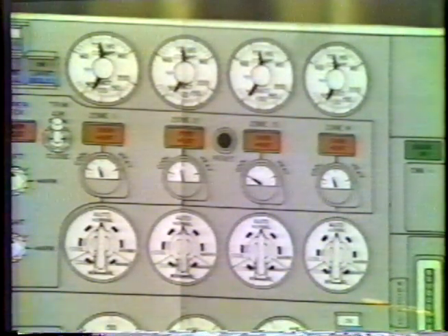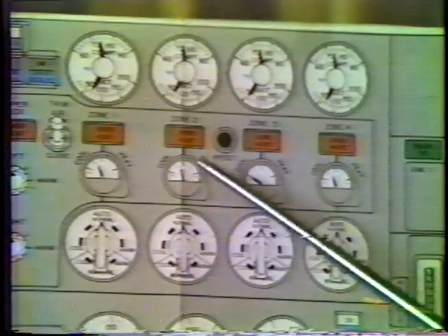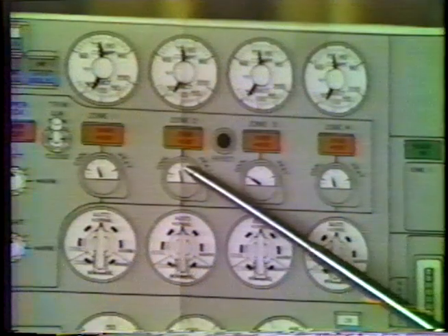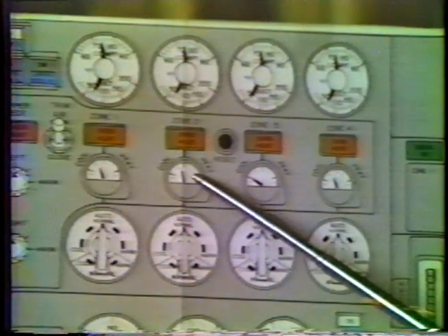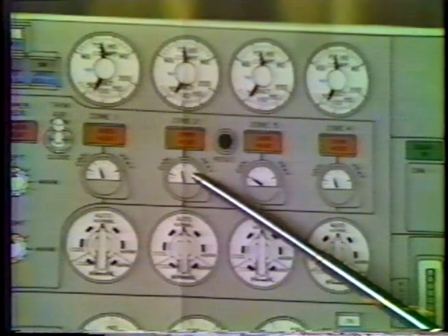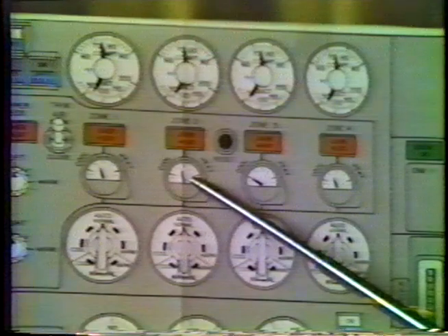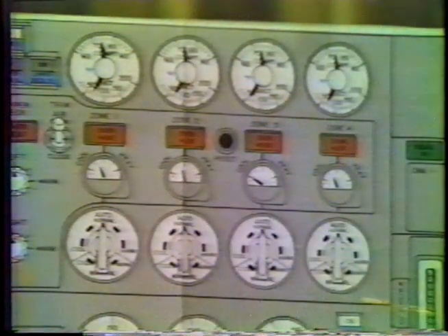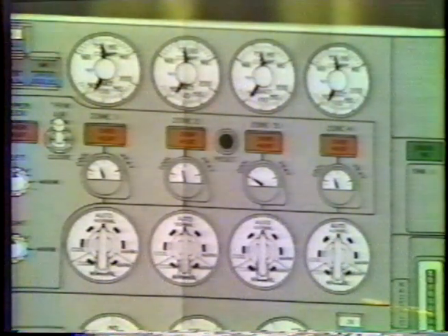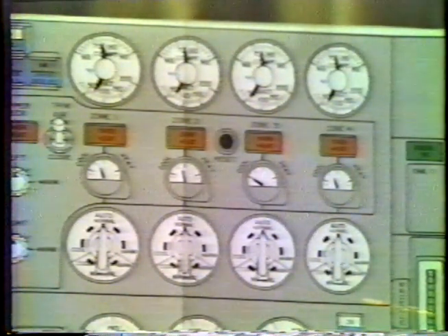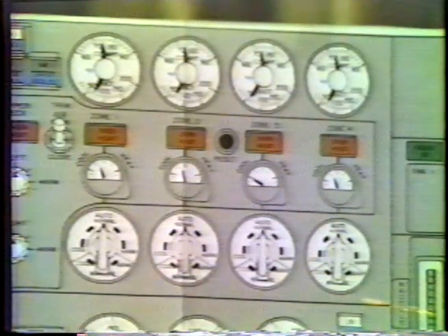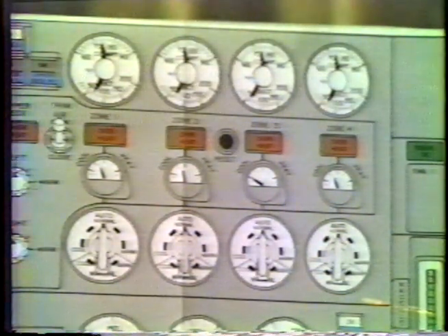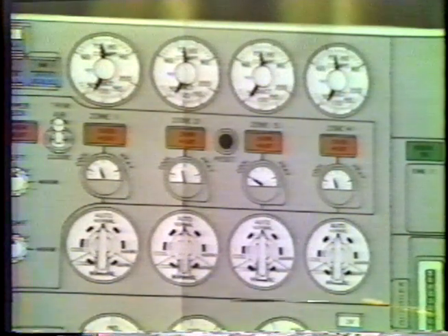To give you an example, the conditioned air is the size of a saucer. The trim air is the size of your thumb, so it doesn't have too much control. The trim air is straight bleed air off the pneumatic duct, and at least one pack has to be open to get trim air. It's downstream of each of the 3 pack control valves.